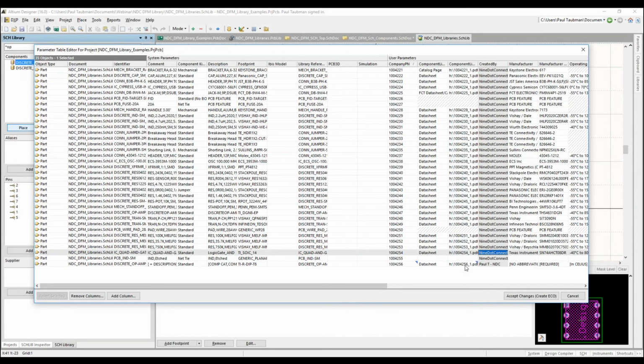I have to make sure that at least I change my data sheet name to something that's useful. We always recommend that you copy those down from the websites, because when parts go obsolete, people from the manufacturers remove those sheets, and you always want to keep that sheet with you. Who it's been created by, I'll leave this here. In terms of the manufacturer, again, this is really nice because I don't want abbreviations, but if I scroll down, I can get the exact spelling so that I will have it correct every single time. It makes it really easy for sorting as well.